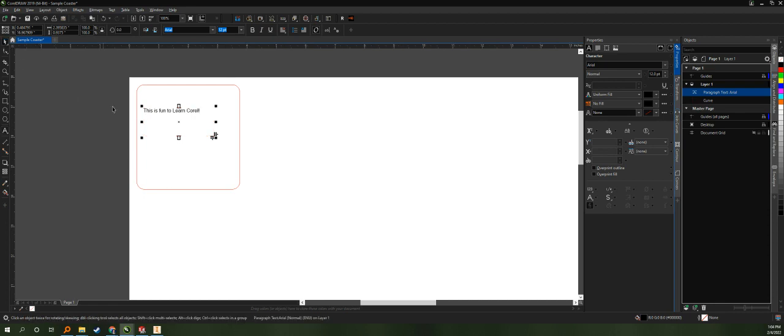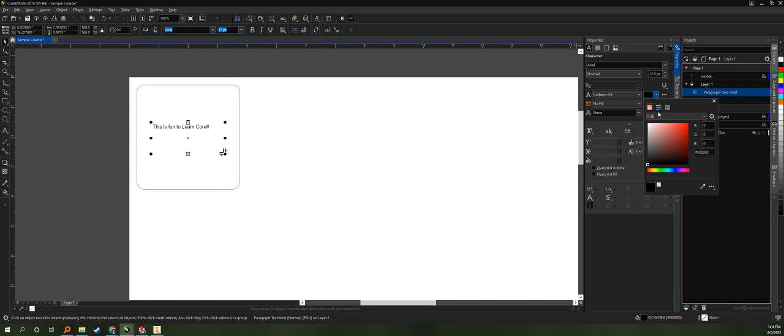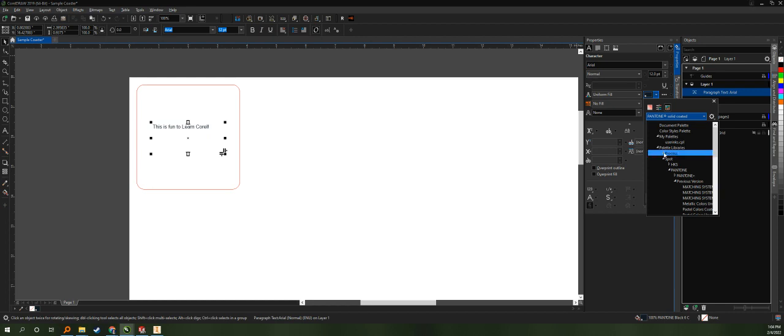Go back to my pick tool, and now in this I can set the fill, uniform fill, and it's going to be a color black. Now it can't just be any sort of black. Once you get into the colors, click this rightmost palette option, and you'll see the Show Color Palettes. When you click that, there's going to be a drop-down bar here. Click the drop-down, and under Palette Libraries, Process, Universal Laser Systems. That'll give you the colors that we use that the laser can pick up on.